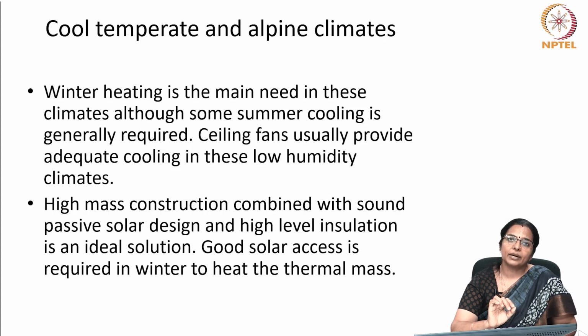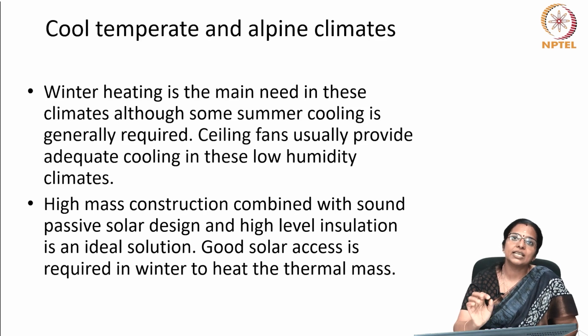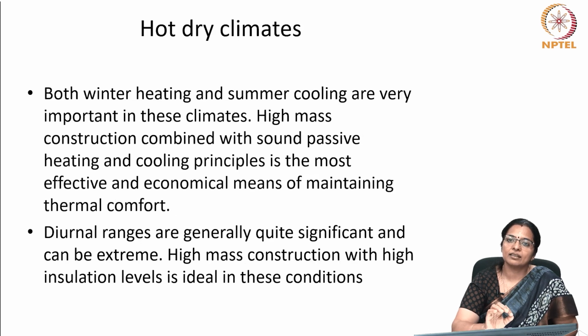In cool, temperate and alpine climates, winter heating is the main need, although some summer cooling is generally required. Ceiling fans usually provide adequate cooling in these low humidity climates. High mass construction combined with sound passive solar design and high level of insulation is an ideal solution. Good solar access is required in winter to heat the thermal mass.